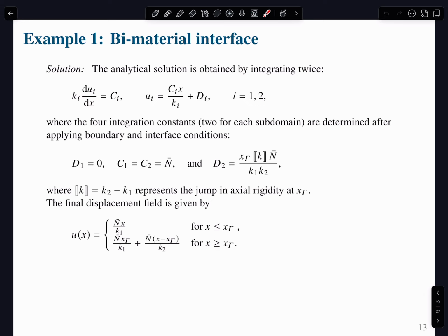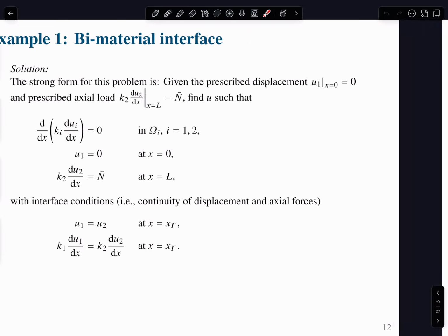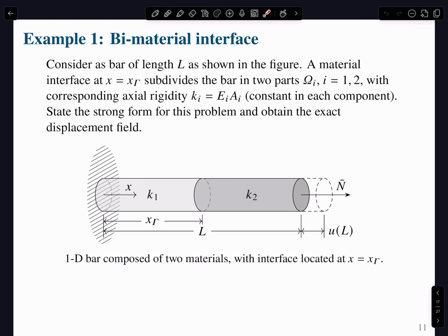And so what you're seeing here is essentially the displacement of the portion of the bar to the left of x, which makes a lot of sense. So at the location of x gamma, you are going to have a displacement that is essentially the deformation of the entire first subdomain. So again, if I look at the problem and I isolate and I put my n bar here, so this is my n bar now, I'm going to get a displacement at that point that is just the deformation of this whole first bar, okay?